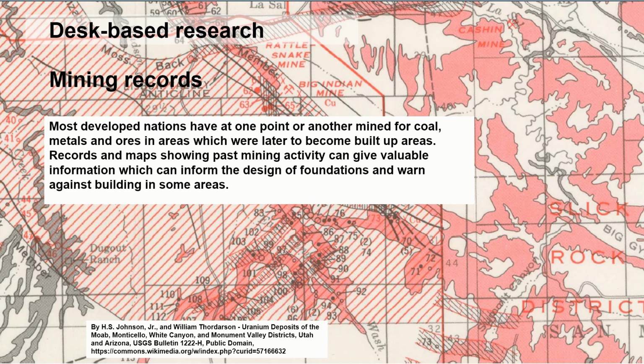The south side of Glasgow was a very heavily mined area, and it's not uncommon for areas that have mines to later experience the ground collapsing as the material in the mines gets washed away, and this can cause sinkholes, and in extreme cases, whole buildings sinking into the ground. So understanding from a mining record whether there's any danger can help you design your foundations, or potentially help you decide the location of the buildings over the whole site. Or indeed it could tell you that the whole site is not the best site to use.